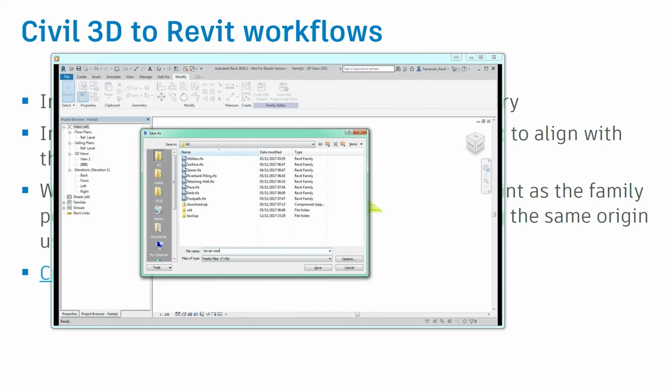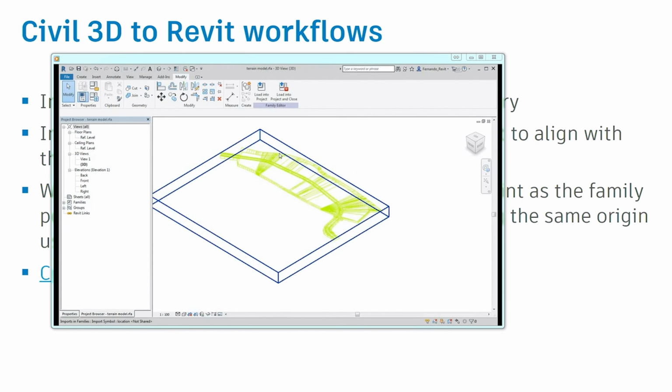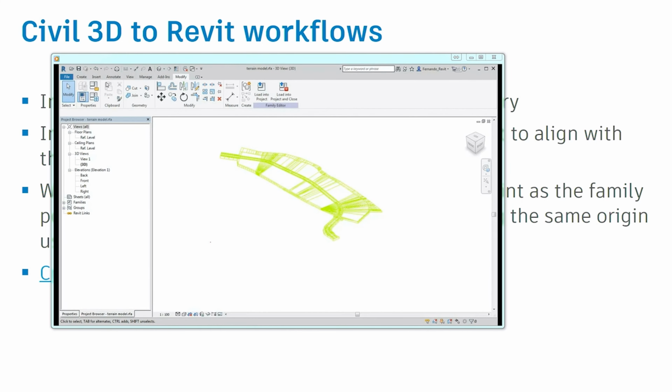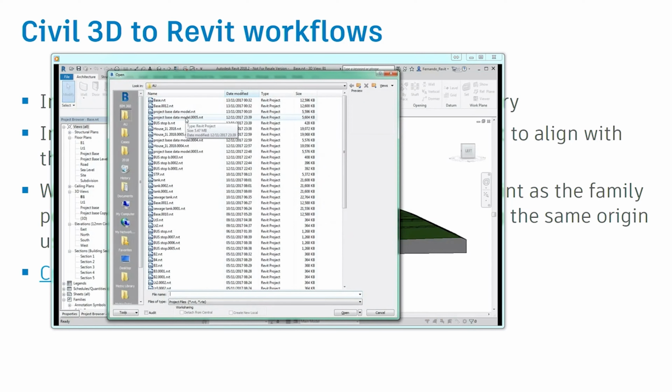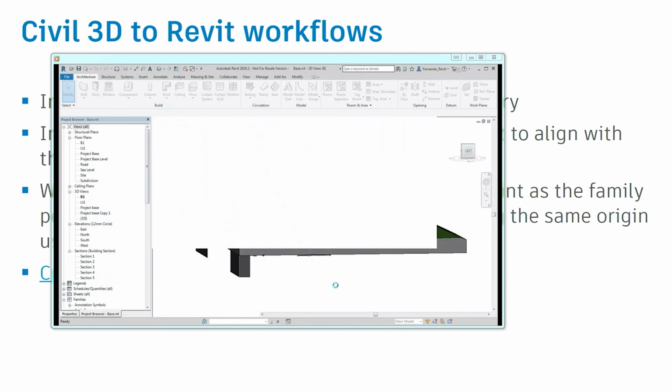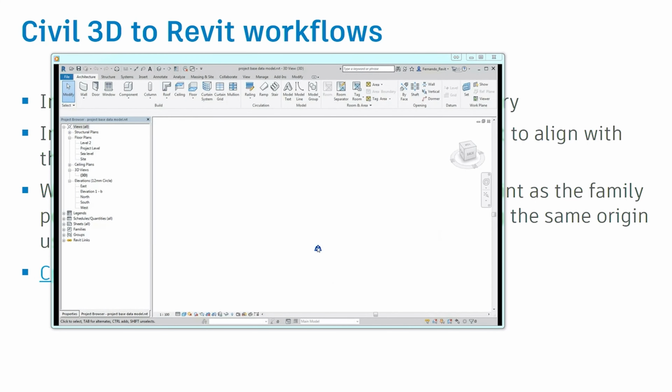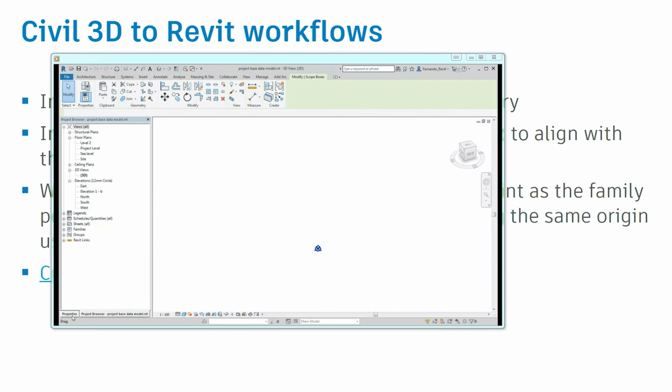The project base point is more for when we are integrating multiple Revit files. But to integrate the survey file, the external files from AutoCAD, into our project, we should establish a survey point inside our project space, and not something 3,000 kilometers away, which is going to create troubles, objects coming in skewed, and stuff like that. So you see now, I'm loading the family, and I'm going to pick that point there.